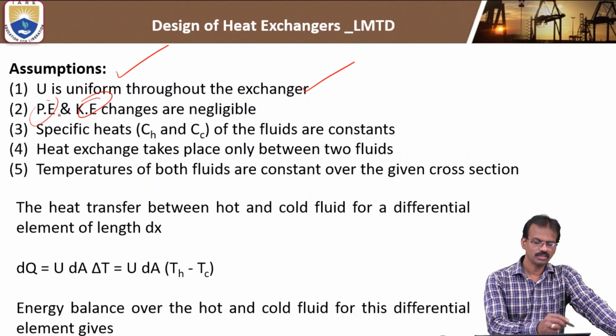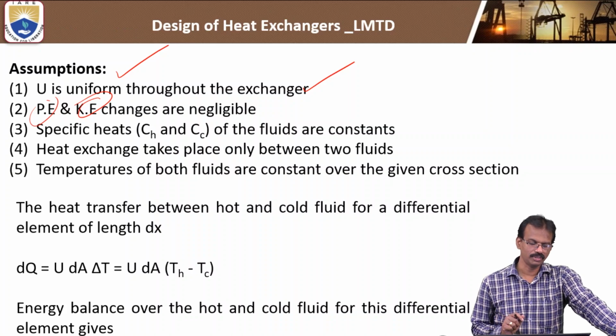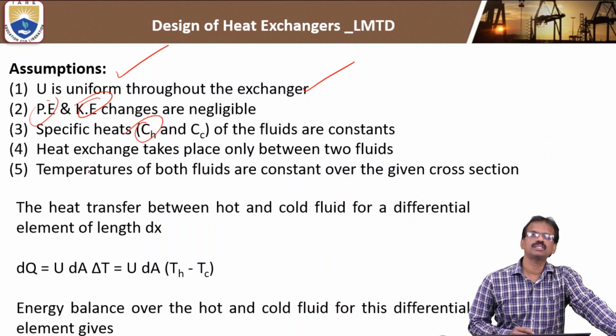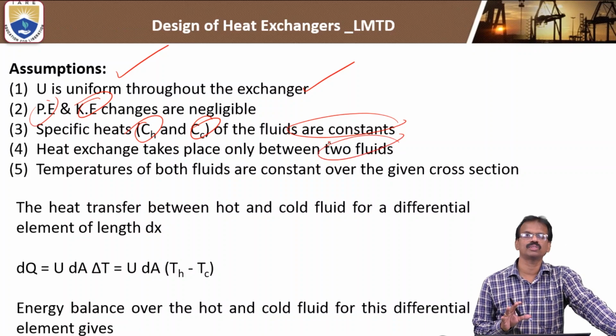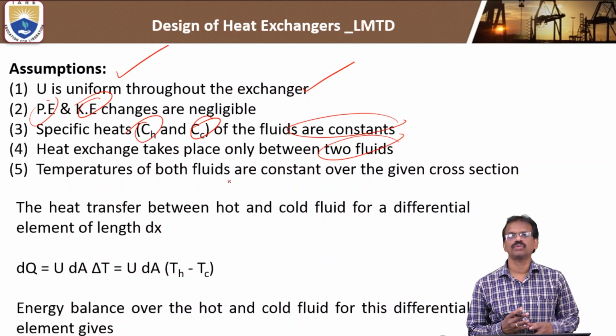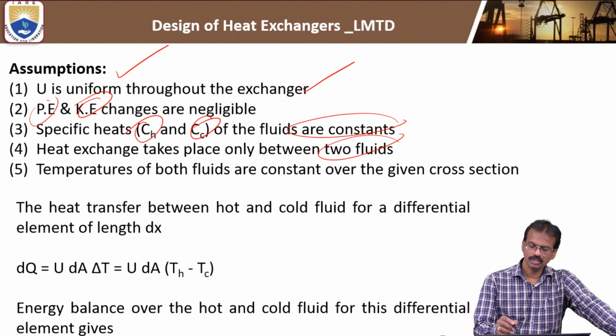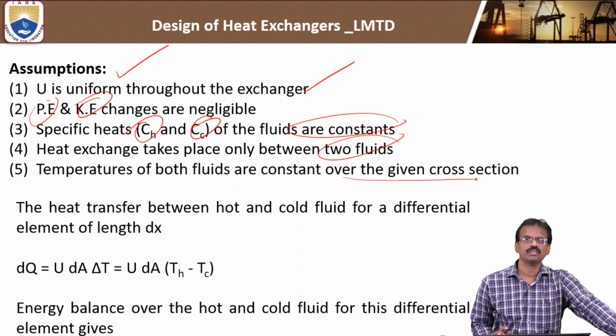Potential and kinetic energy changes are negligible. Specific heats Ch and Cc are assumed constant. Heat exchange takes place only between the two fluids. The temperatures of both fluids, hot inlet to hot outlet and cold inlet to cold outlet, are constant over the entire cross section.